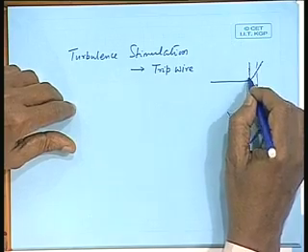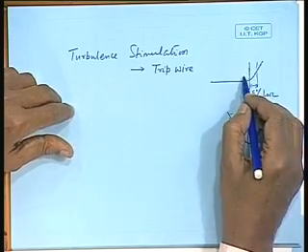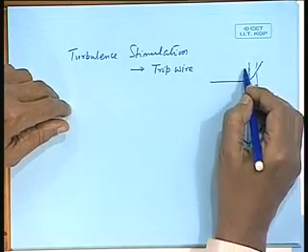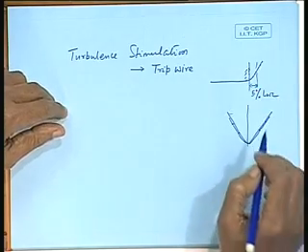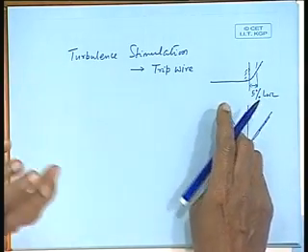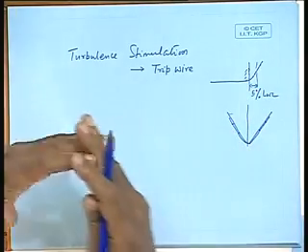Now, suppose I have put a tripwire here. What is the guarantee that the flow here is turbulent? The initial flow here will be turbulent, but because of pressure difference, we have seen there is a relationship between pressure and velocity. Because of such pressure differences, the velocity may further drop. If the pressure difference is high, then velocity may drop further. If velocity drops, turbulence again may fall, because the regional Reynolds number will come down again.